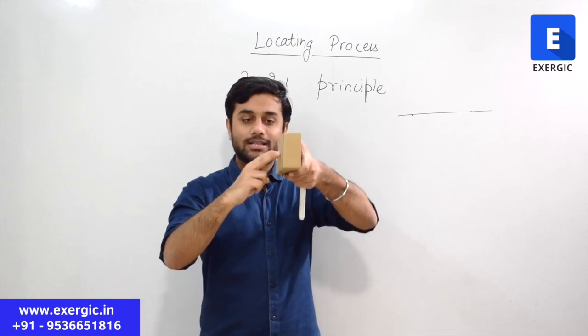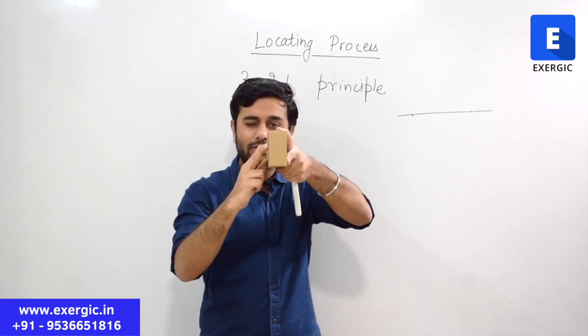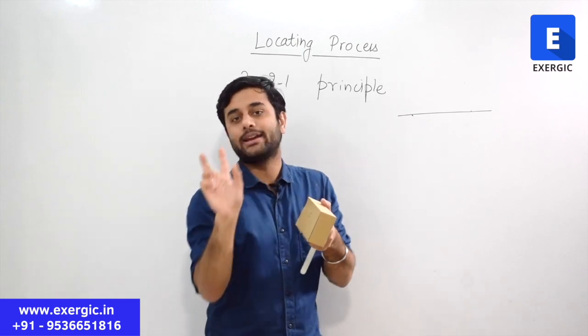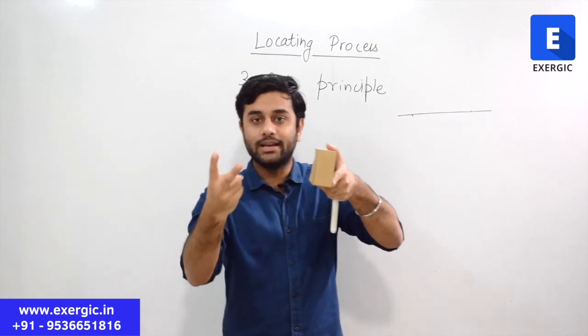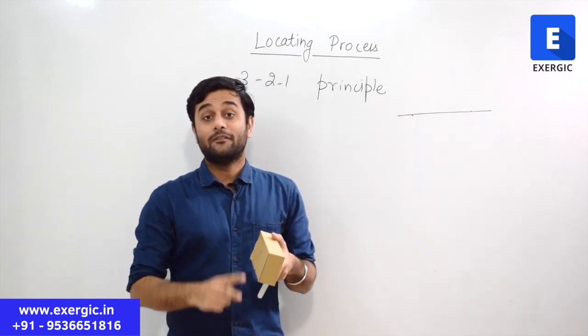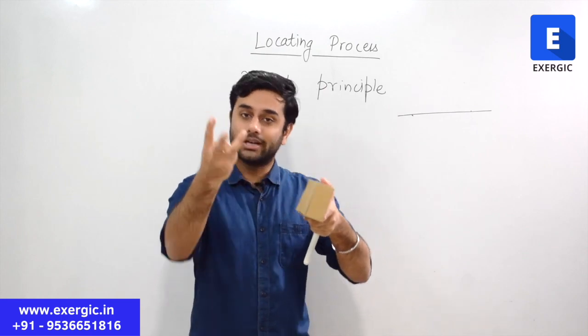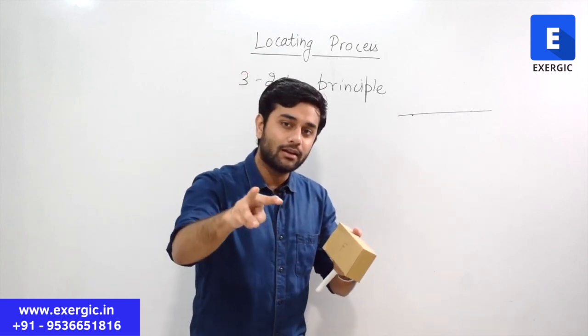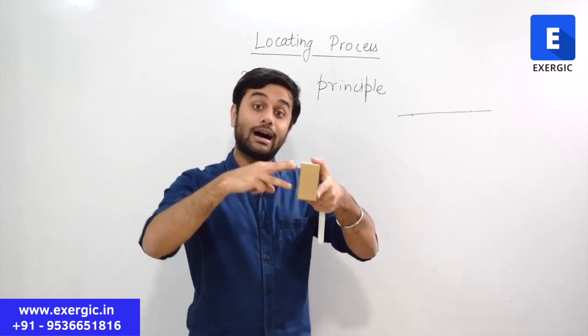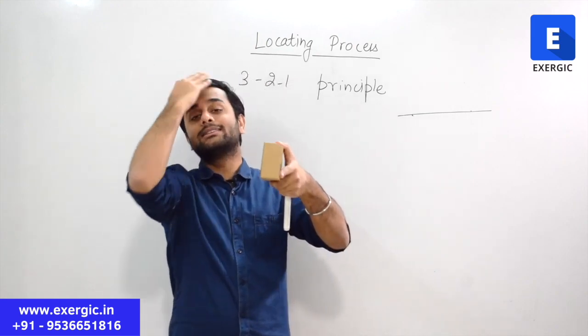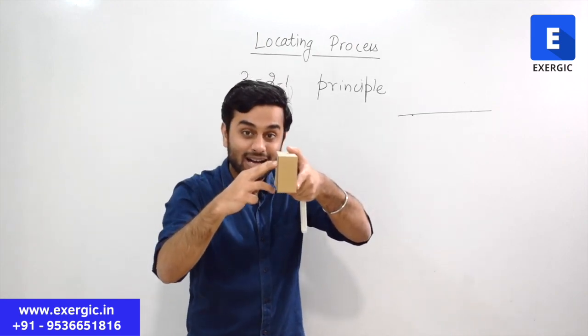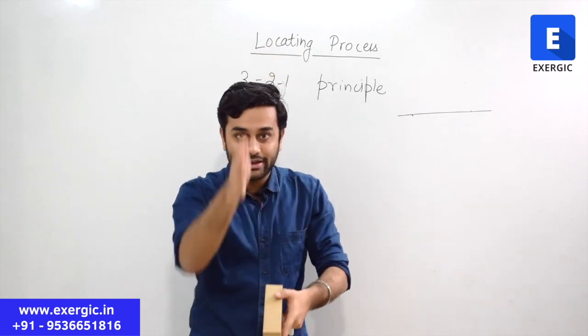We cannot define this plane perfectly; there will be slight misalignment, very slight, when you try to define it using the 2 points. When you add one more point, because a third point is needed to define the plane, again there is no surety that this third point is going to pass exactly through the vertical plane.